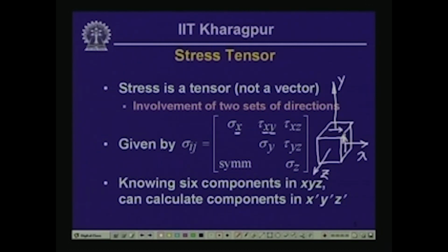You notice that as soon as the shear stress was occurring on the top horizontal plane, we introduced another shear stress occurring on the right vertical plane. Similarly, you are going to have two more shear stresses on the two planes that are not visible from the front.